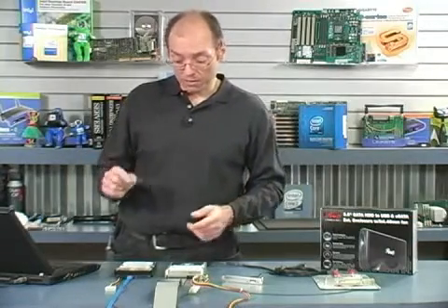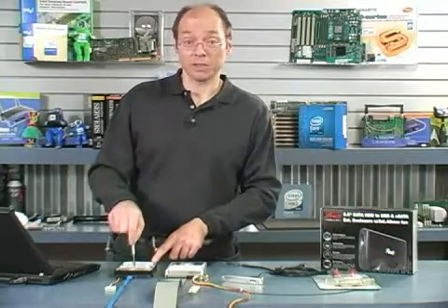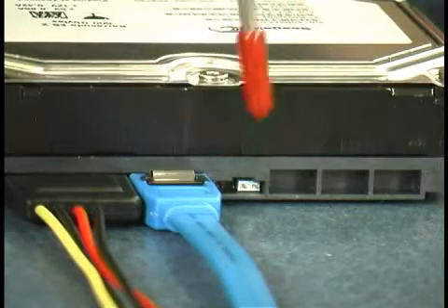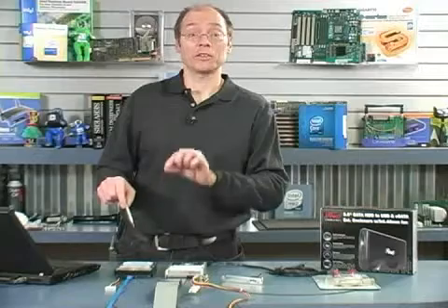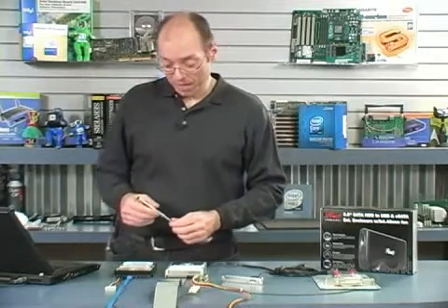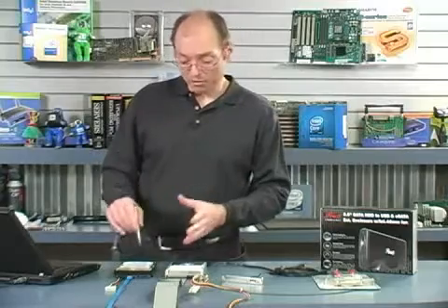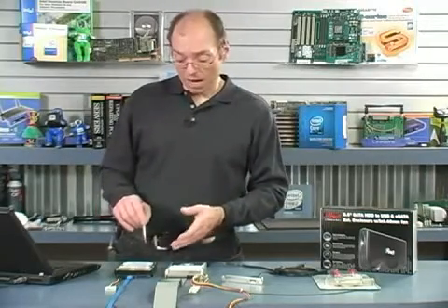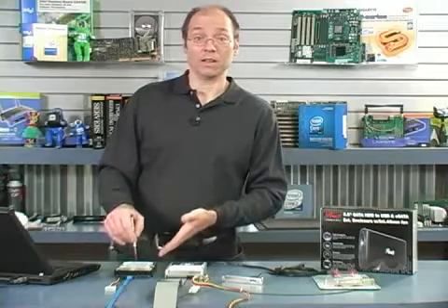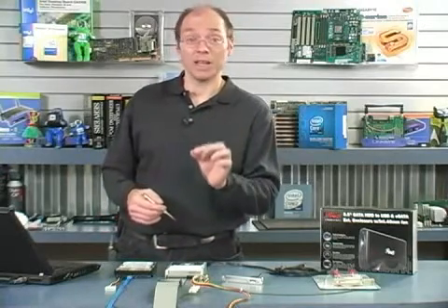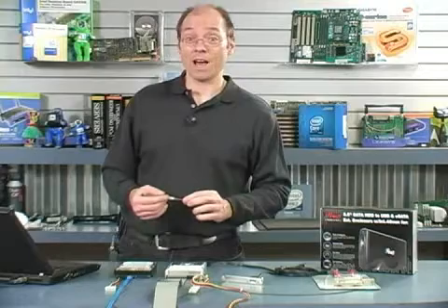So almost all of the serial ATA 3 gigabit per second drive manufacturers are including a limiting jumper on the drive that will knock the drive down to 1.5 mode. In other words, cut the drive speed in half. And guess what? Virtually all the drives I've seen lately ship with that jumper enabled. So I just bought 6, in fact, of these serial ATA drives. Every single one of them had the limiting jumper in place to knock it down to half the speed.